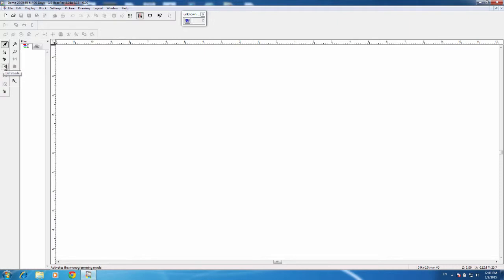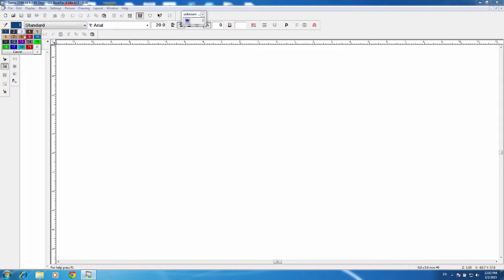So in order to insert some text, I will left click on the text mode. When I do, there's a couple of things that I'd like to look up on this bar that's going to tell me some information on the text itself. First of all, the needle number. When I input the lettering, right now, the needle will be set on number 1. We can change this now, or we can change it later. If the thread that I'm using is on a different needle, I will want to click on the needle and choose what number I'm using. So if I'd like to use needle 8, for example, I'd press 8. And now it will allow me to stitch the name with needle 8 on the machine.